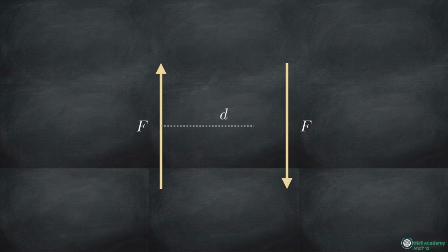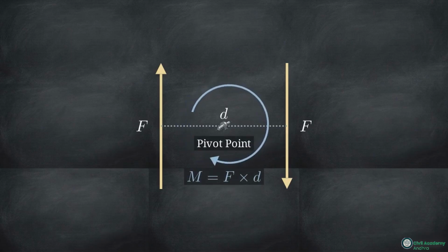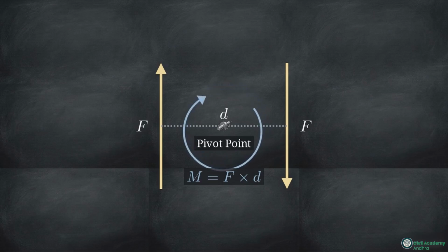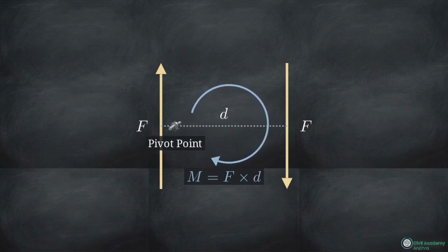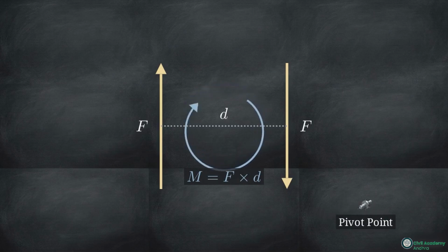We can isolate rotational force even further into a state called a couple. A couple occurs when two forces of equal magnitude run parallel but in opposite directions, separated by a defined distance. Looking at this diagram of two parallel arrows, we see the difference between a couple and a standard moment. A standard moment depends on a pivot point and causes both pushing and spinning. A couple generates pure rotation, independent of where the pivot is located.